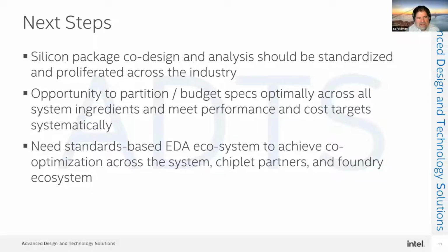And is this database proprietary to the tool vendors, or is it a neutral format that you can write additional tools to interface with? We are looking to make it neutral and agnostic to the CAD tool being used. I would use LEF/DEF as an example for moving data from silicon design databases to package databases. The tools may have some proprietary algorithms to read the databases, but the goal is that the databases move between different tools seamlessly. Which is exactly, Ira, the third bullet: we need a standards-based EDA ecosystem to achieve the co-optimization, so that it does not become tied to a particular vendor, and the databases can be exported from each of these EDA tools in a neutral format which could be read by some other tool.